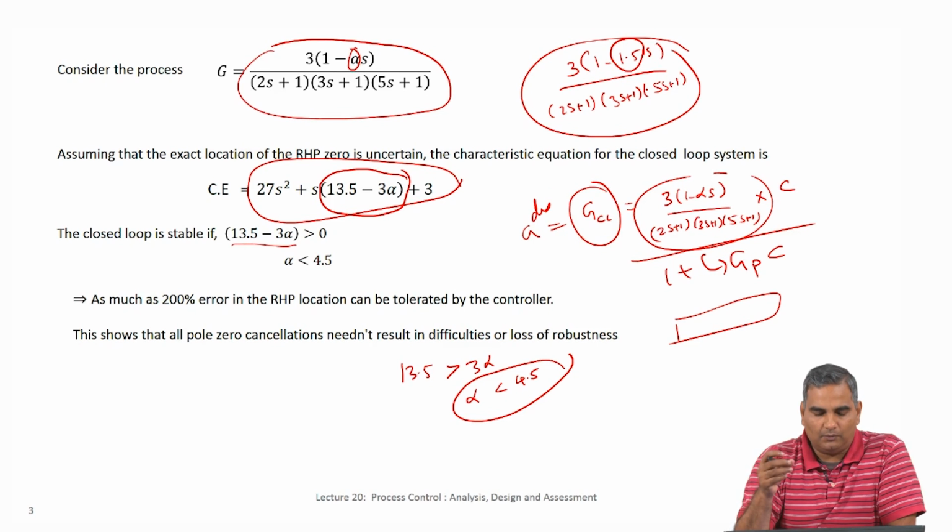One last thing I would like to address here is I do not want you to get the feeling that we are not using a model at all in your undergrad control. We do use a model, in designing the controller. For example, if you take Ziegler-Nichols tuning, you use a model to figure out the limit of stability, and then all your controller tuning parameters become a function of the model parameters in some sense. Slightly conceptually different is the controller itself having the direct model equations in its design, like C is 1 over GM times G desired by 1 minus G desired.